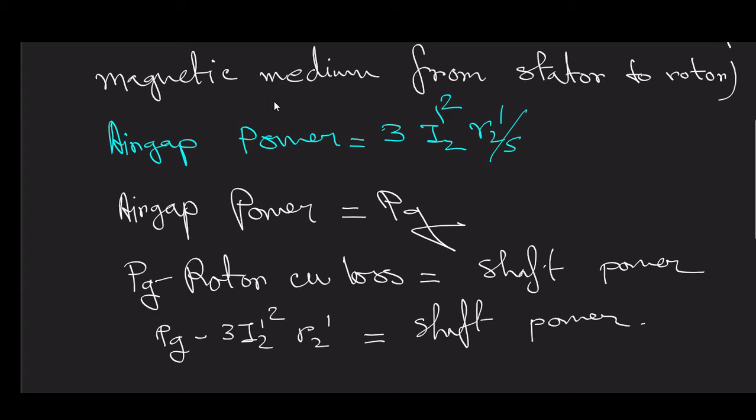Now you may raise a question that, sir, as you have said, the rotor circuit can have a different number of phases. It is not necessary for the rotor to have 3 phase. It can have 5 phase, 7 phase, 6 phase, 2 phase, any phase. So how are you saying this? For understanding this, I have already mentioned that this whole thing is the rotor equivalent referred to stator. So it was from our equivalent circuit per phase to three phase conversion.